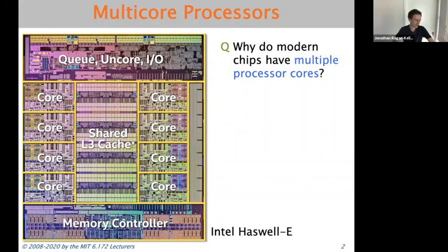Good question. Before we get to that, what's the uncore? Uncore is Intel jargon for, like I was saying, all that stuff, like all the specialized logic, potentially GPU logic, potentially the on-chip network to connect all the different components, potentially things like USB or Ethernet or PCI controllers, reflecting the cultural centrism of Intel architects, where the core is the fun, important thing, and everything else is second class.